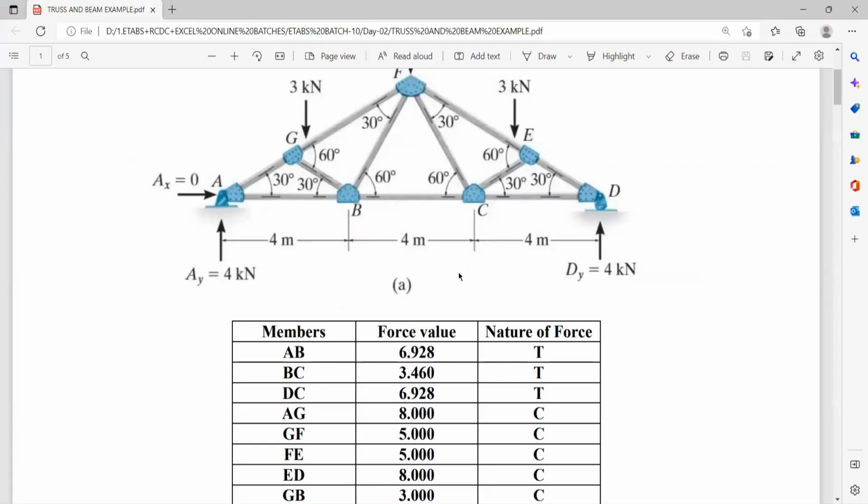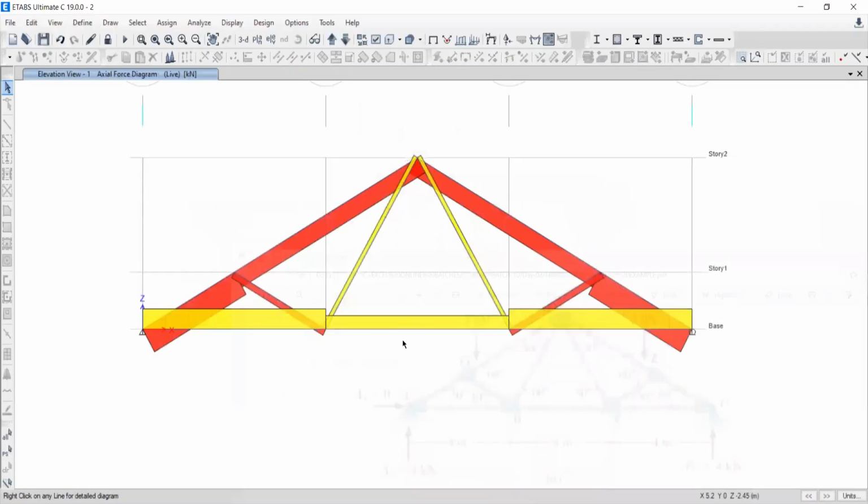Coming back to your manual calculation result. So our manual, we have a trust on this manual calculation. So it is 6 point, your result is showing 5 point. Okay. Come to BC, 3.46. BC, where it is? Yeah, 3.46. Come back to your ETABS. 3.48. Yeah, up to certain extent we can allow it.